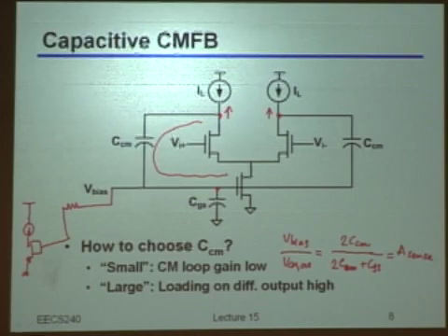So if this is the sense gain, but anyway, as you noticed, we're not even using an amplifier in this loop. So is this enough? That's our question right now. Well, actually, my claim is it is enough most of the time, because as you see, even if the sense gain is at most 1, for a very huge CCM, what happens then? What is the path? So if you really write the full expression of the loop gain for the common mode.